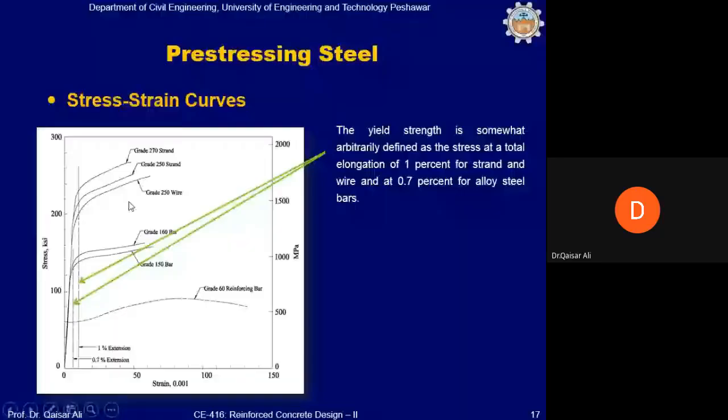It is very important to determine the yield strength in the lab, because as I said quite a few times, the steel must not be stretched close to its yield strength, because then the steel will permanently set. So it is important to accurately calculate the yield strength of steel from a lab test.